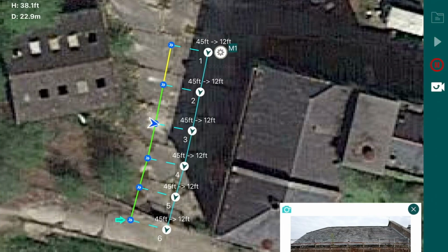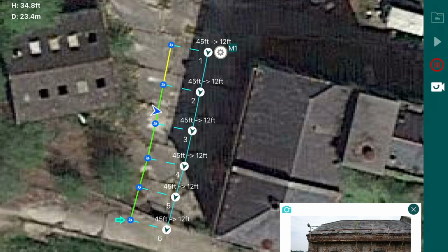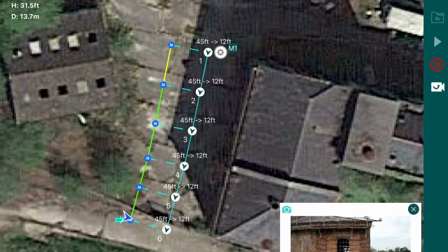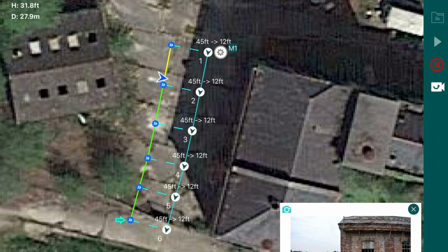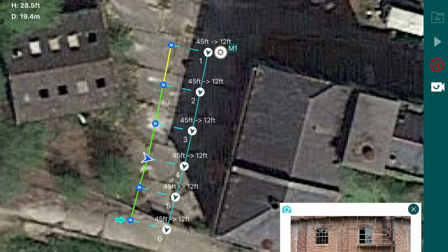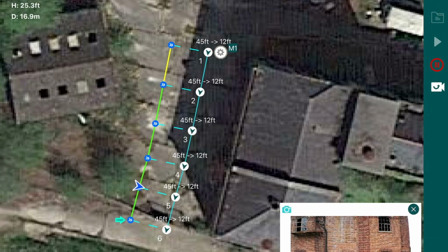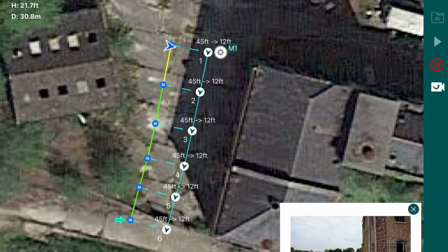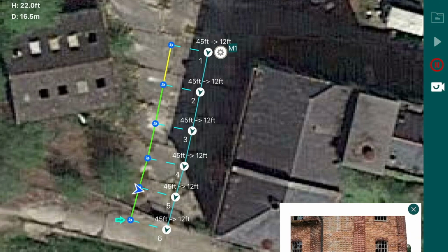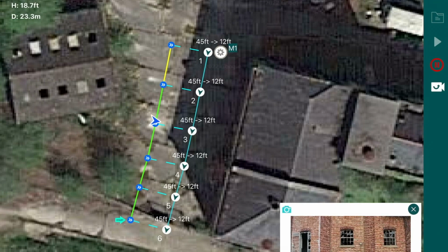Now, what a lot of people don't understand is that the ground sampling distance doesn't have to apply to just ground. It can apply to any surface. So if you're capturing the data vertically, it could be essentially the facade that is being mapped in the camera of the drone that represents the ground sampling distance. Albeit it should really be called facade sampling distance or surface sampling distance or something like that. So essentially, ground sampling distance does not have to include the ground, it has to include what is being mapped.